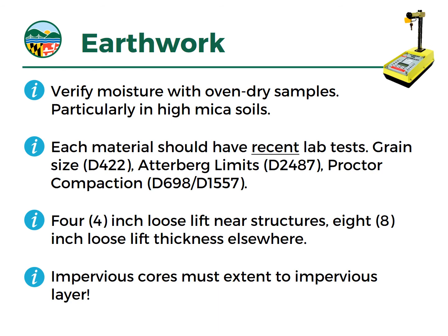How confident are you that the material you're getting delivered is what you expected, what you bought, particularly when it's a manufactured aggregate, because you needed a specific gradation. So grain size, Atterberg limits, and Proctor compaction again. Standard Proctor is the standard for all dam projects, not modified Proctor, even though modified Proctor is typical for most other construction.